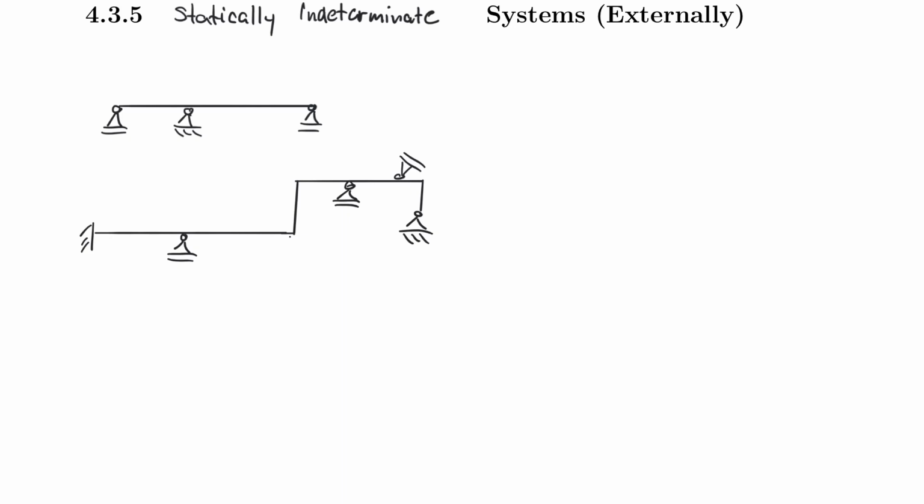And so now the one thing that you need to understand about statically indeterminate systems in this class is how many times is it statically indeterminate. So can you guess which the degree of statical indeterminacy is for this system? Go ahead and do it, and after you finish pausing the video, I'll solve it for you. I have 1, 2, 3, 4, 5, 6, 7, 8. And so this is to the 5th degree, right? So 5 times statically indeterminate, so 5th degree.